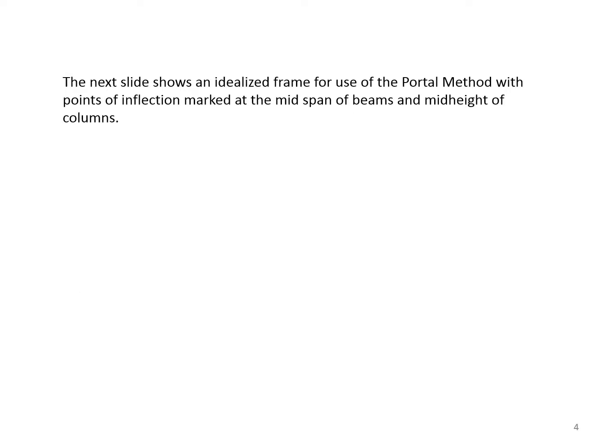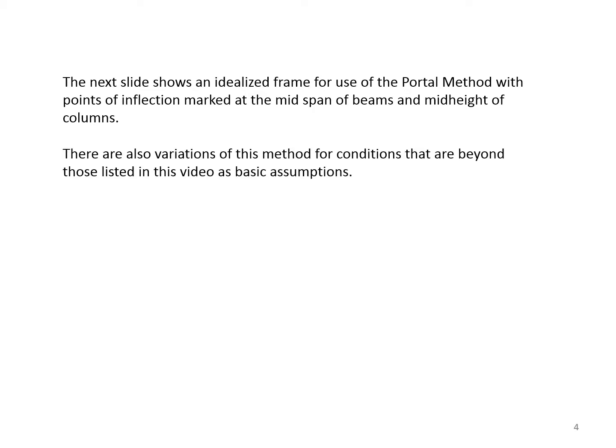The next slide shows an idealized frame for use of the portal method with points of inflection marked at the mid-span of beams and mid-height of columns. It is also mentioned that there are variations of this method for conditions that are beyond those listed in this video as basic assumptions.